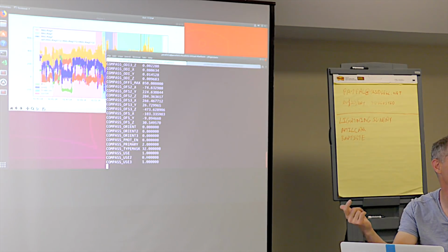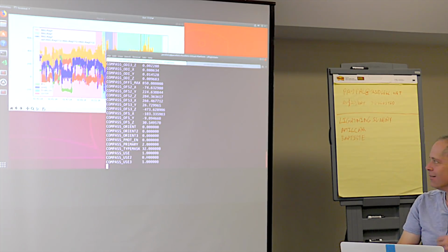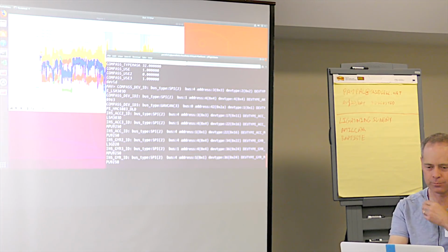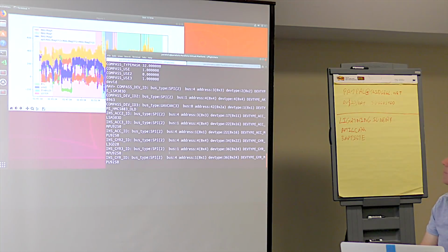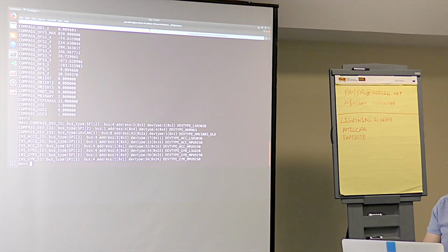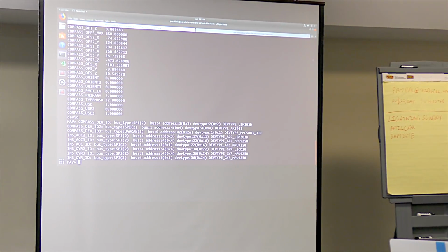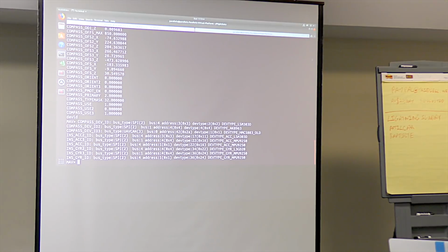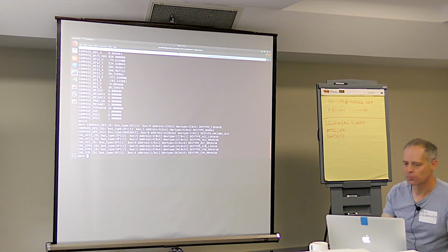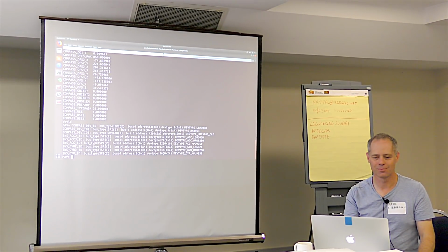So this is the question: in this instance, what compass is this log using? Type the command DEVID, all one word. That says what the compasses are. You widen that a little bit. So you can see the first one was an SPI. The third one, which is number 2, is UAV CAN. Compass primary 2 is actually the third compass. So he's basically set the compass primary as the CAN compass. And it is enabled because use 3 is 1.